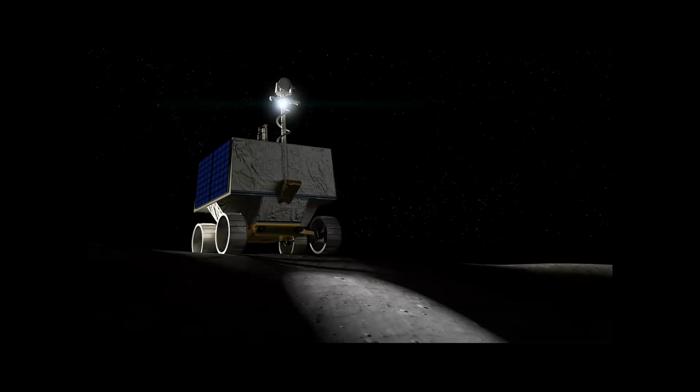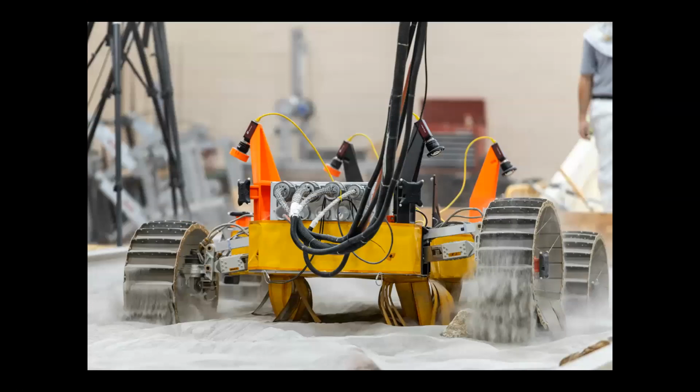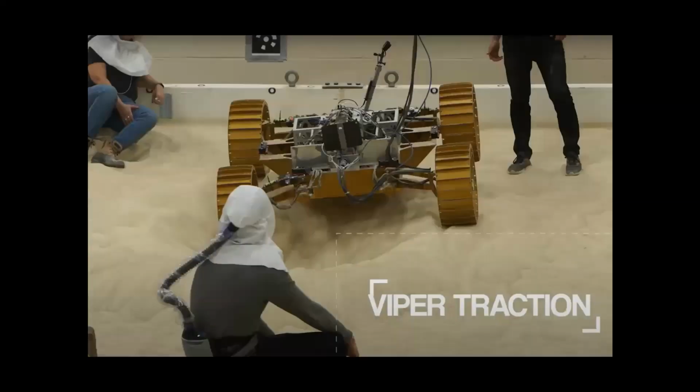VIPER has been tested quite a bit at NASA Glenn's SLOPE Lab throughout its development, starting with simple single-wheel dynamometer testing in simulated lunar soil and rocks, and then graduating to complete mobility subsystem testing in loose granular soil and rocks, and on slopes too.